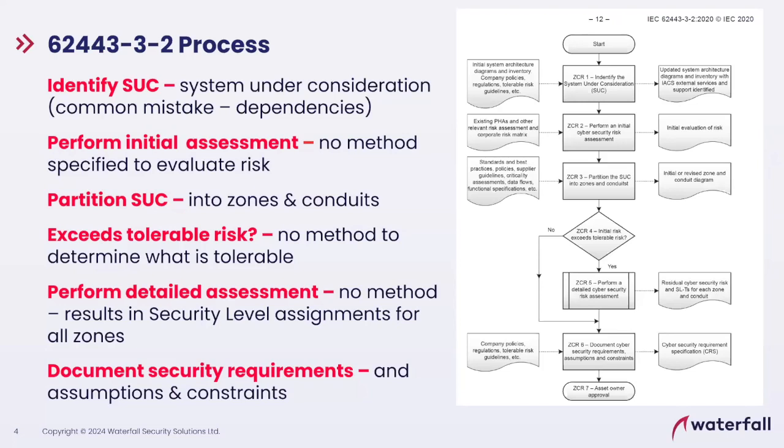Our IT teams say, look, if an employee leaves the company, I am required to terminate that employee's permissions company-wide within 24 hours. How do I do that? I need a permissions manager, identity and access management, IAM. That's code for Active Directory. I put an Active Directory into my IT network. I put all my employees in there. I'm done. All of my OT systems, if I want to log into, let's say the HMI server, not the HMI itself, but the HMI workstation to do a backup or something, it's all on Active Directory.